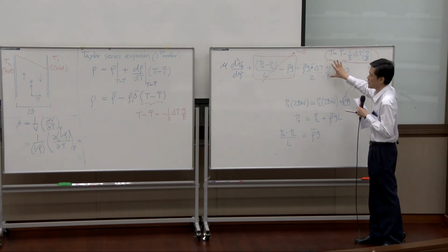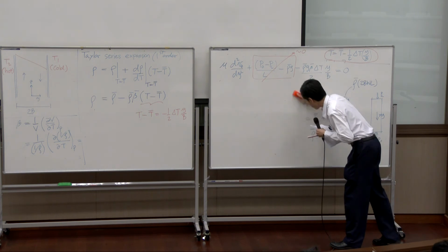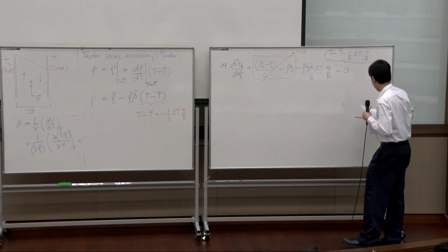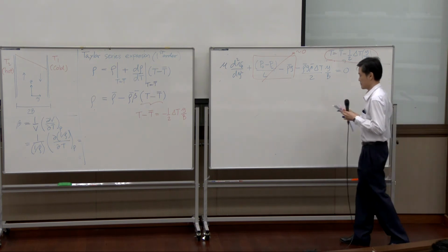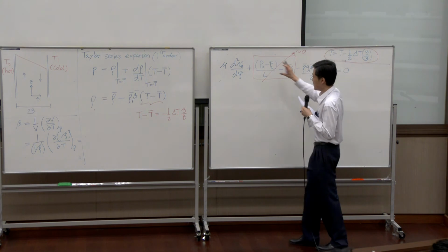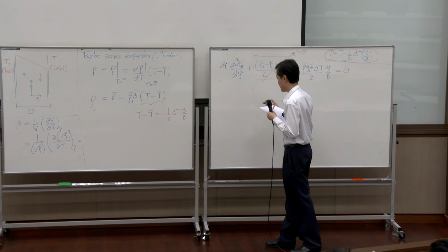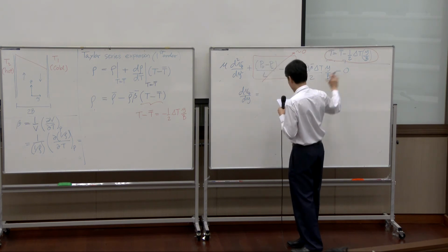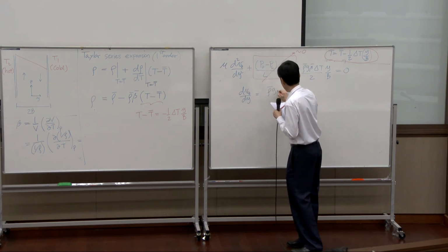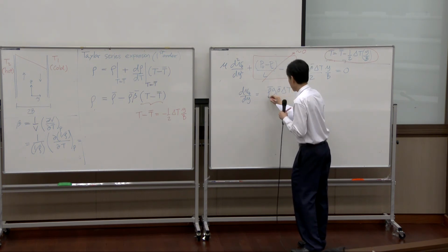So from here, basically you need integration. Let me erase this. If we integrate, moving this to the right-hand side, integrate it first, I will get dvz by dy equal to everything on the right-hand side, that's rho bar g beta bar delta t over 2.